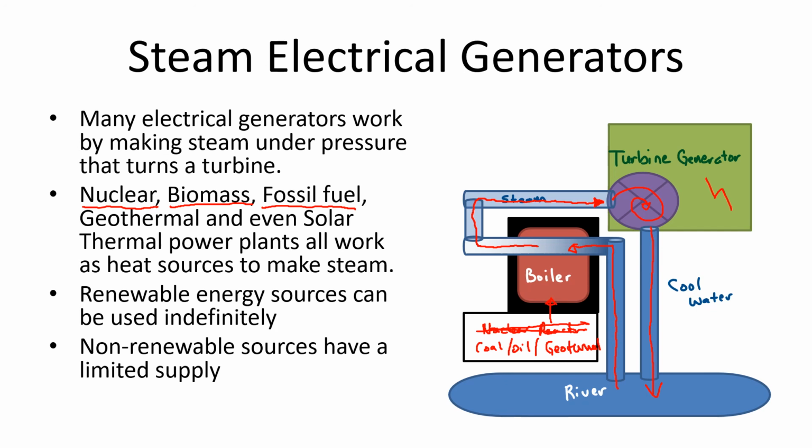And finally, a place where you have a lot of sunlight, you can use the heat energy from the sun. There's a couple places in the world where this has been used. Places like in the middle of the desert. I think there's some in Iraq and some desert places in Africa where they have intense sun, 300 days out of the year, and so you can use that to heat. Usually they superheat some oil, and then that oil is used to boil water, make steam, and turn a turbine.